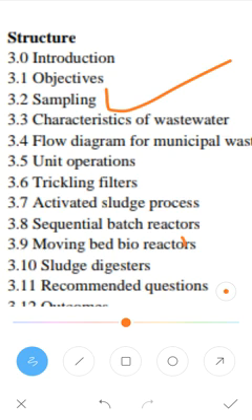Next, for the integrated sample, for certain purposes the information needed is best provided by analyzing a mixture of grab samples collected from different points simultaneously. Using the discharge-weighted method of equal width increment or equal discharge increment procedure or equipment, this can be done.